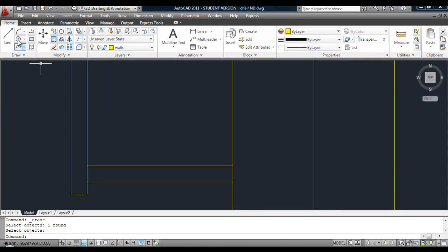You're going to raise up this circle. Do the same again for the little batten. Draw a circle from this point now, 25 millimeters. Draw a line from the intersection, come out this way 25 and down to there. And raise up the circle and draw a line from there to there. A line from there to there.